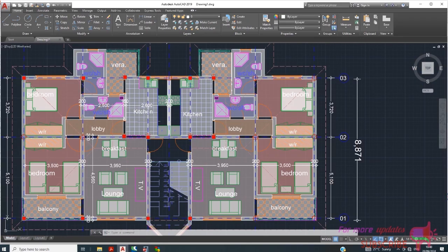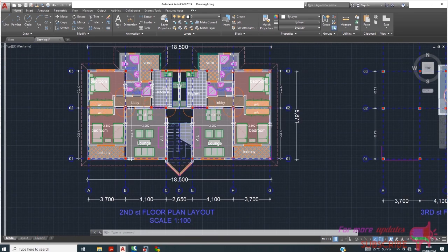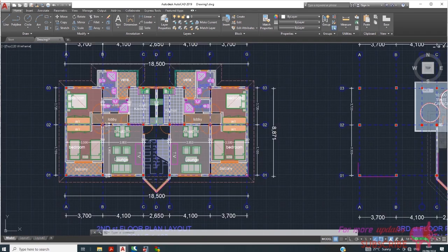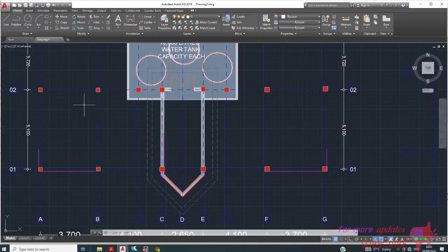So we have to determine also the place where we're going to add beams. Obviously I prefer my beams to be primary. Primary beams basically means beams that are transferring the load from slab directly to the columns. So in this position, I should maybe have a beam here and a beam here and also there and there. But this can be a partition wall.